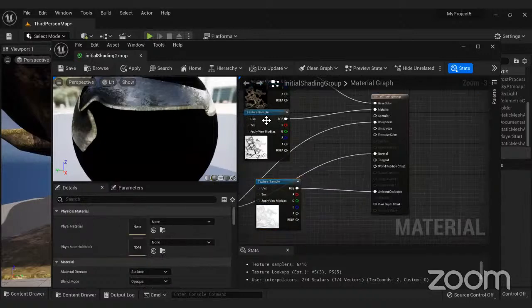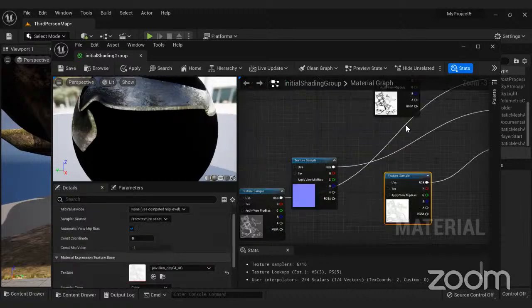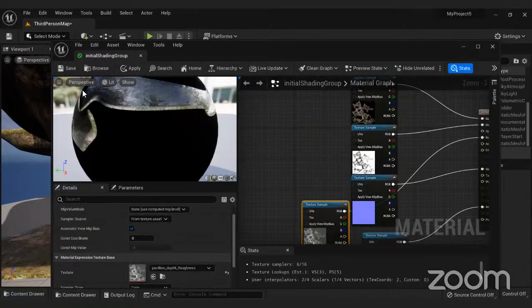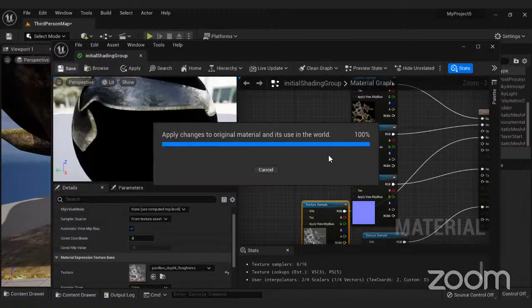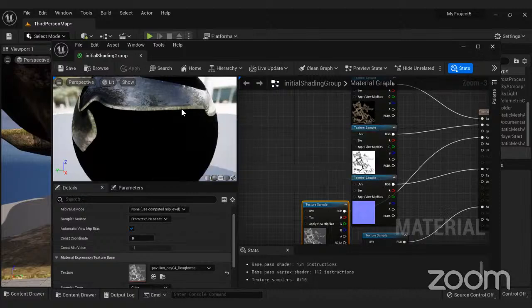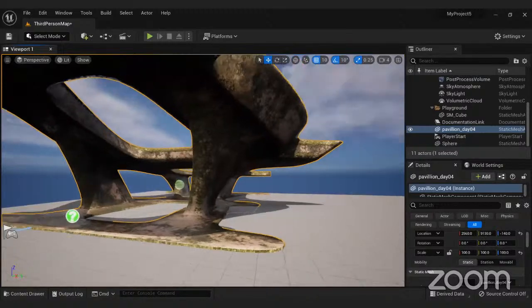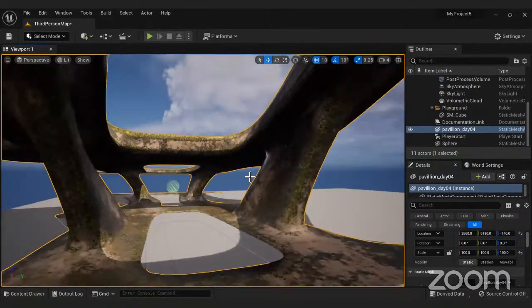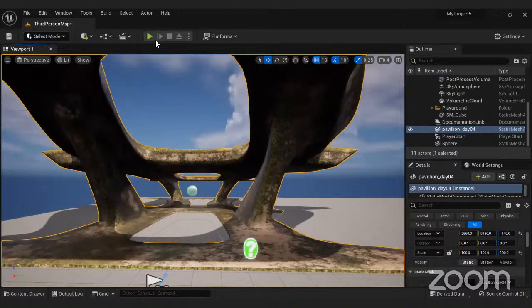By default, the naming and everything is all there. If you click on one, you can see the texture PNG file is called albedo, so you put that in the base color. This one is called metalness, so you put it in the metallic. Just like that, you complete everything and save. You click save over there, and it's going to update the shader. Then you should be able to see your entire texture on your object, just how it was from Quixel.